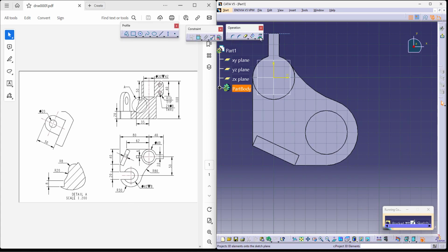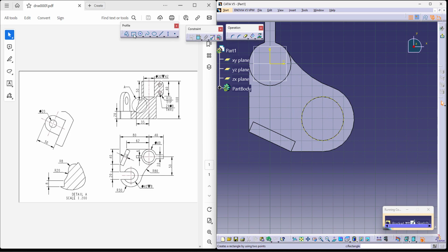Next, we can directly use a pocket command to start removing the shape. You can use references as well if you want. It's easier if you use references. Now I would actually require an infinite line as a reference because I require the concentricity. So I use those as my references.